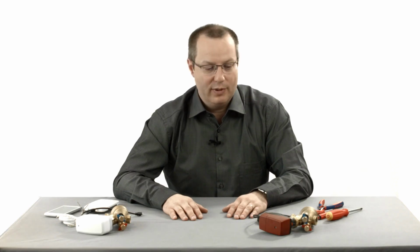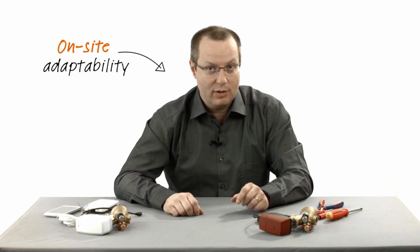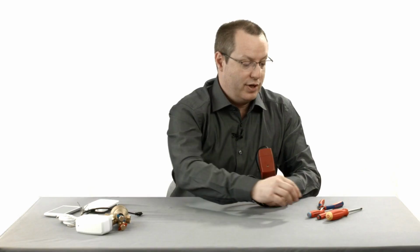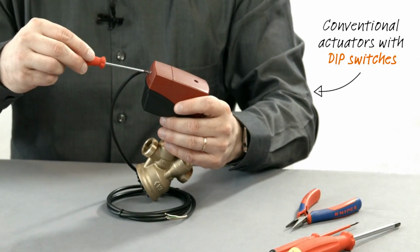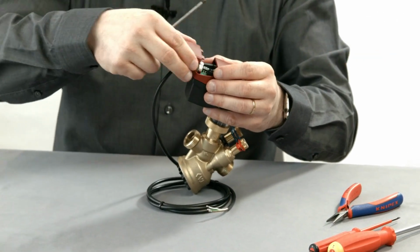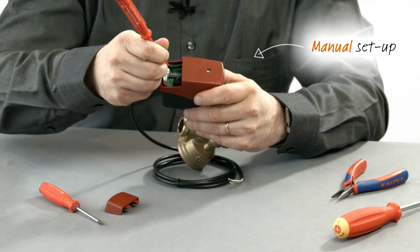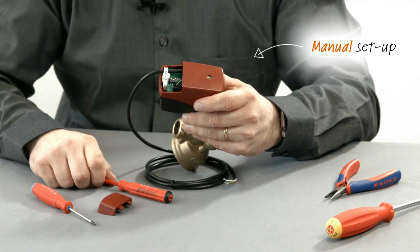Let's talk about the setup of actuators. As you know, actuators need to be adapted in their configuration to the control systems in which they are fitted. To do this kind of configuration with traditional actuators, what you need to do is to get access to the actuator, bring along with you tools allowing to open the cover or compartment of the actuator, and access a rack of dip switches or jumpers, allowing one by one to make certain configuration choices in the actuator.